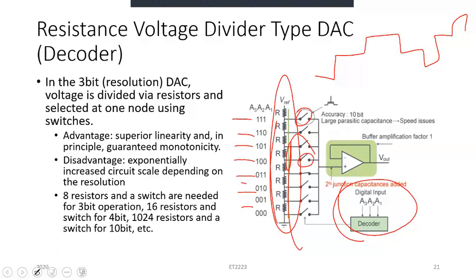It's a fairly simple approach, but the problem is, say now if we need to have this circuitry repeated for each of the states. So here for a 3-bit, we had say 8 states. If we have 4, we'll need 16. So likewise, for a 10-bit, we will need 1024 states. That would be a significantly larger and impractical circuitry to use. For smaller converters, this would be a fairly simpler option.